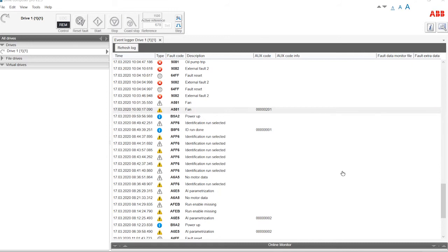And I see that I found it over here, but it doesn't give me anything useful. So I go to next, and there I see fan programmable warning, main fan fault function, cooling fan feedback missing. And then it gives you what to do. So this is an easy way to do fault finding. And the auxiliary code itself will be over here. It says check your auxiliary code and identify what fan is broken. So it's in the format of XYZ.